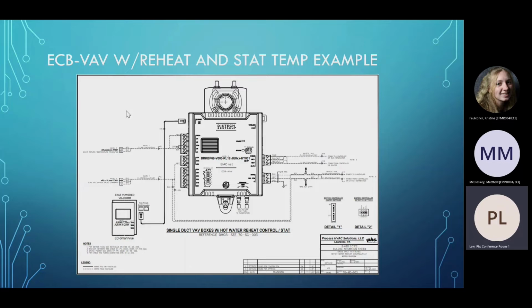So in this case, in the previous case, is the PID control in the Distech, or is it in Delta V? Both. There is a Delta V command which overrides the Distech PID, but if we lose comms, the PID will still be active in the Distech controller. Normal control would be the PID in Delta V stroking the valve. Yeah, absolutely. However, the carbon is only in Distech. That's if the carbon dioxide is too high. That does not live anywhere in Delta V, to my knowledge.